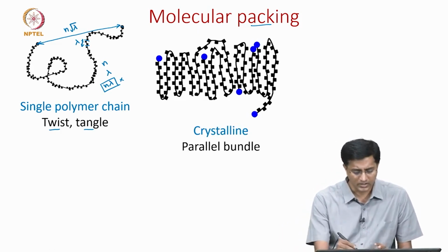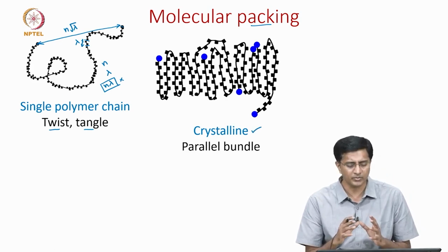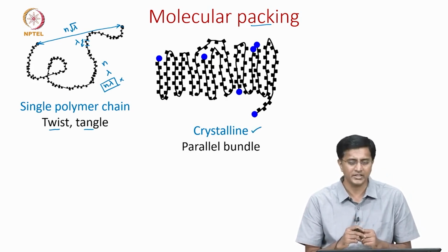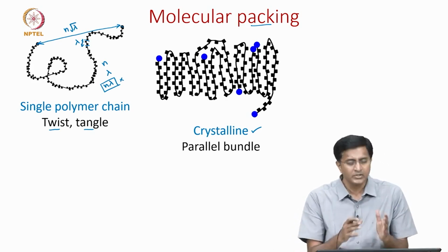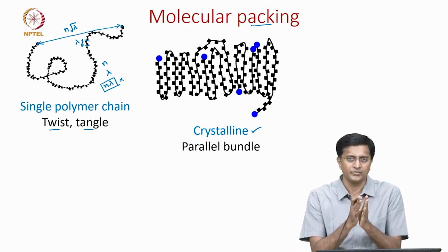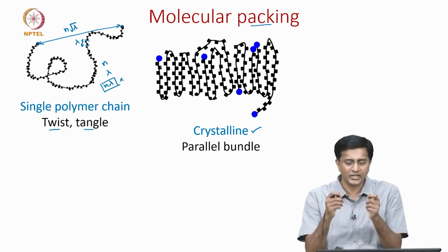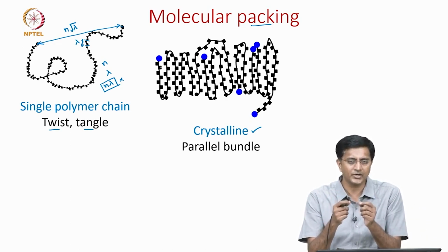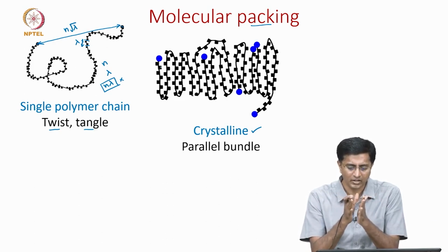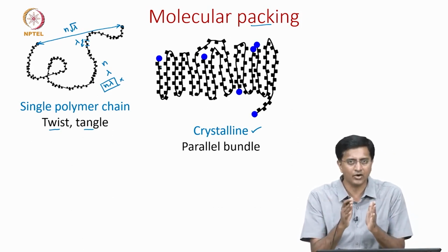So, usually some or few polymers form this crystalline structure, not all polymers, but few polymers form a crystalline structure. What it means is, as you can see here, these polymer chains fold. The reason why they fold against each other is because these hydrogen atoms, when they come close to each other, there are these interatomic forces like the van der Waals forces or the hydrogen bonds which form, and then when they come close, that secondary bond holds them together. So, in this way they are packed very neatly or closely.